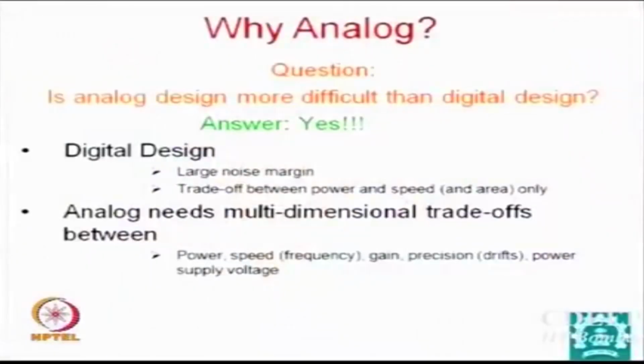Of course there is a trade-off that still goes on there; the major worry is power connected with speed. Larger the power, the higher the speed. This is very obvious, trivial in some cases, because in most circuits the current which you are using is to charge the capacitor. Larger the current, C dV by dt is larger, time will be smaller, as straightforward as that.